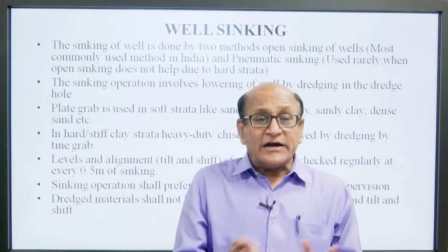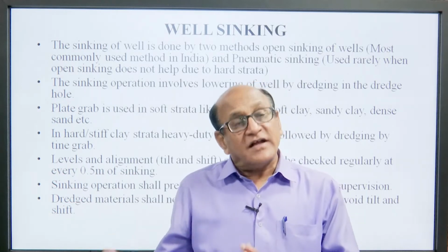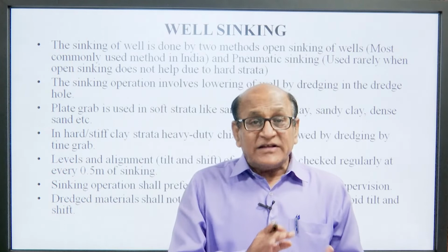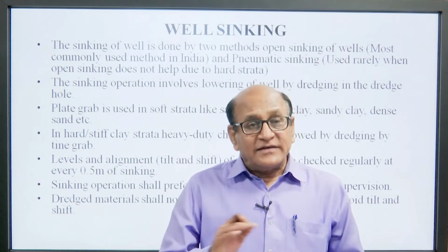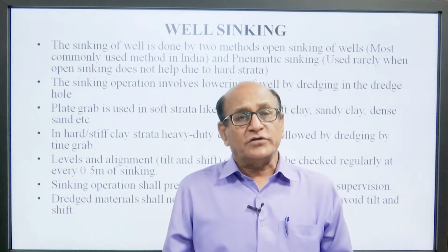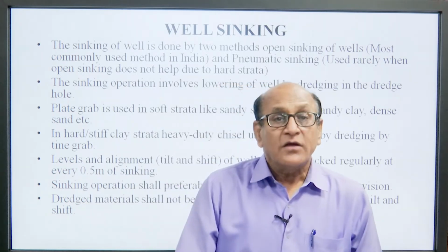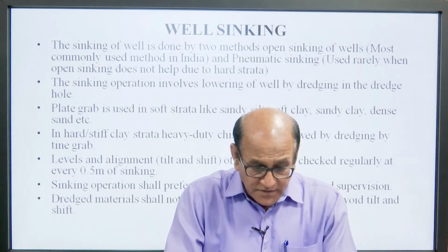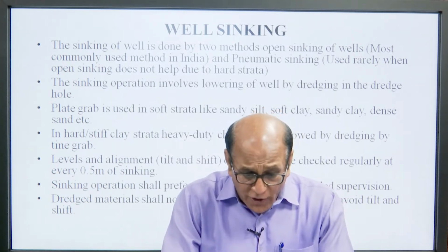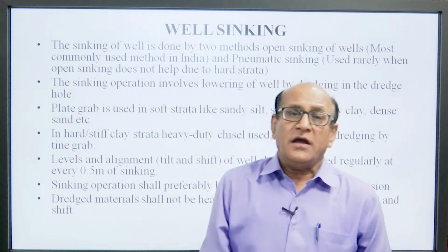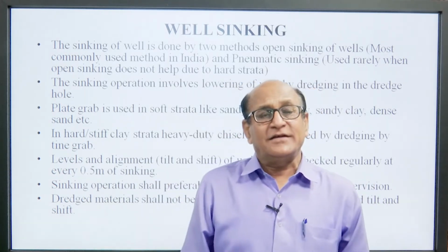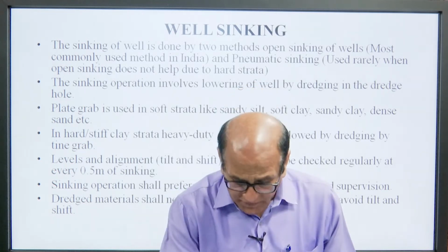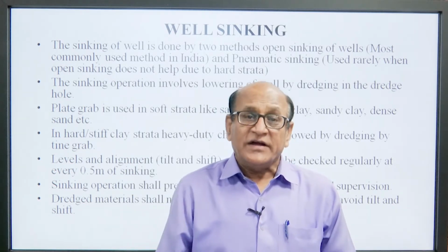This will exert pressure on the constructed well, and this will cause tilt and shift both in the well. Dredged material shall not be heaped on one side; it should be placed around the well uniformly, if not sent outside.